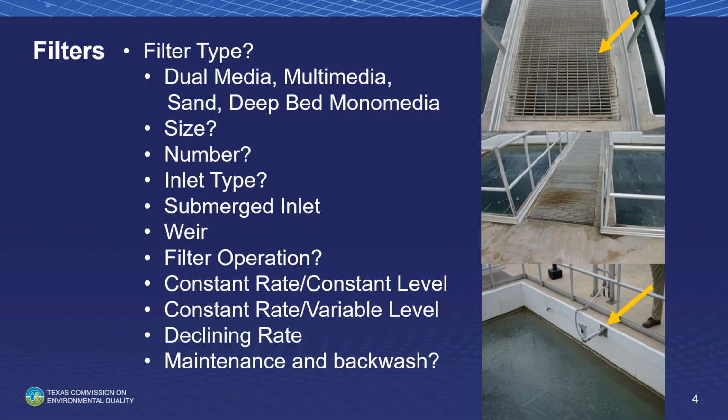Then you want to do this. Let's talk about filters. We talked about the clarification process. There are a lot of different filter types. There's just the old-fashioned sand media filter. There is a dual media filter that contains sand and anthracite. There's a multimedia filter that contains all kinds of different stuff.